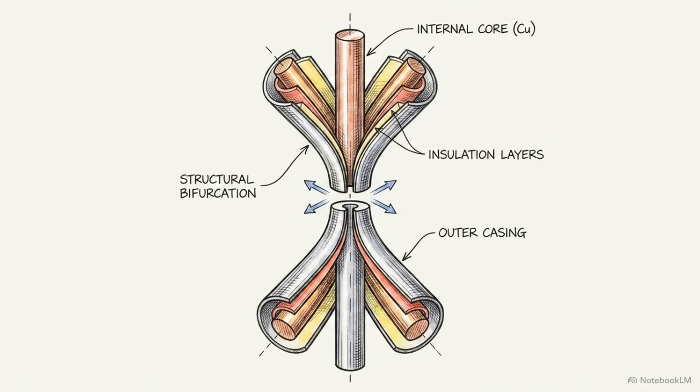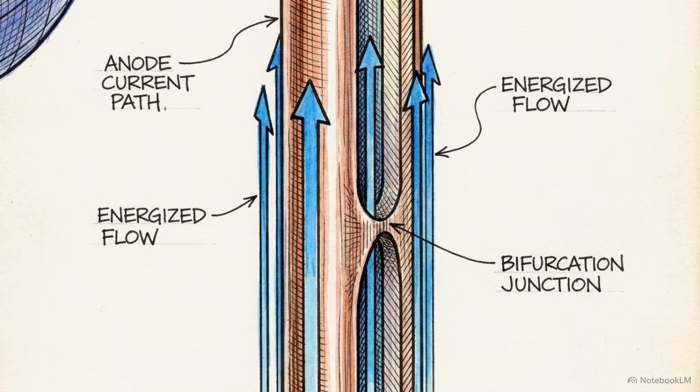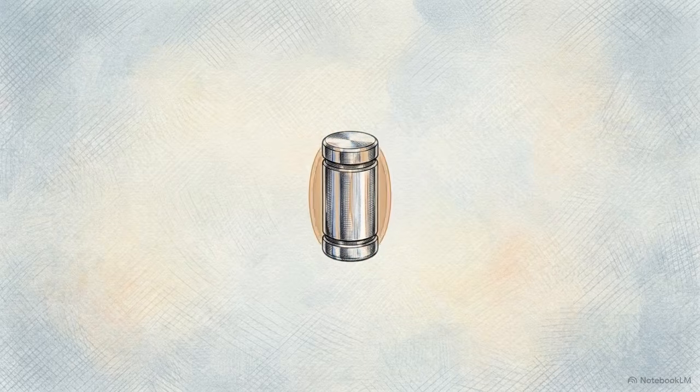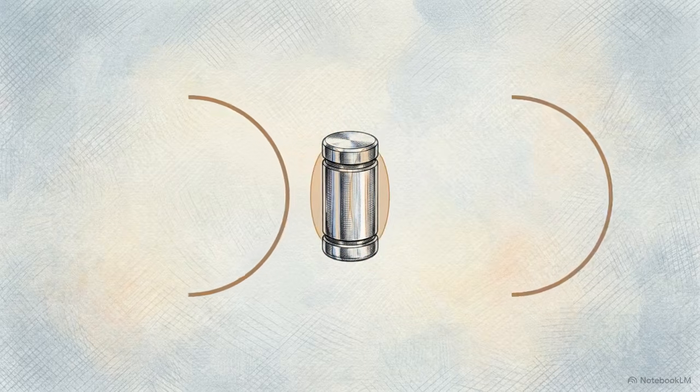We can see this in action using the simplest antenna model there is, the short dipole. It's just a straight piece of wire carrying that alternating current. Right next to the wire, the near field, energy just sloshes back and forth like a spring stored nearby. But as we move further away, the frequency pushes the energy until it eventually detaches from the sloshing near field.